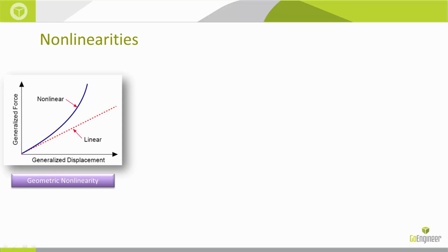So in a linear simulation, SOLIDWORKS calculates the initial shape of the object, defines a small load, and then keeps applying that load to get your final deformation. In a nonlinear study, there are calculation steps, and after SOLIDWORKS deforms the part a little bit, it recalculates the shape and applies the load again. This is a much more accurate process, and realistic for that matter.